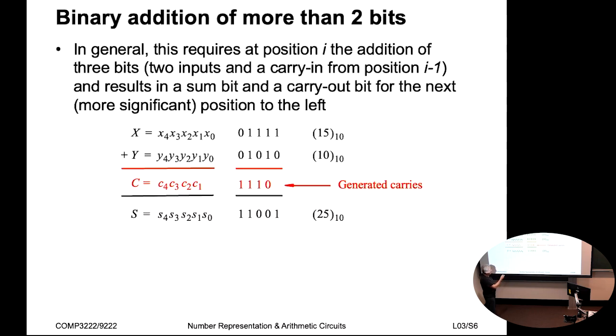So this carry bit is added to the 2 bits that we next want to add together, namely 1 and 0. So we've effectively got 1 plus 1, which is 2, so again a 0 plus a 1 carry. Then we have 3 ones that are being added together, so of course the sum of those is going to be 3, or a sum bit of 1 and a carry bit of 1, right? So finally we see that over here on the right-hand side. Is that clear?